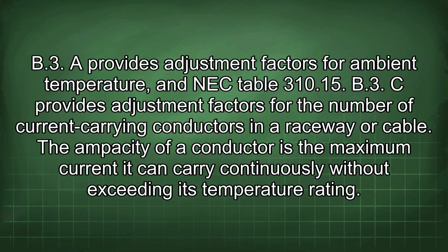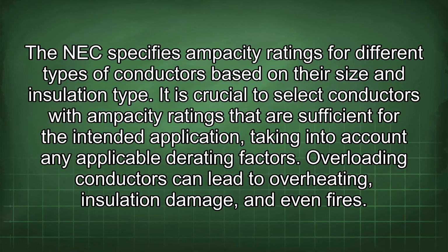The ampacity of a conductor is the maximum current it can carry continuously without exceeding its temperature rating. The NEC specifies ampacity ratings for different types of conductors based on their size and insulation type. It is crucial to select conductors with ampacity ratings that are sufficient for the intended application, taking into account any applicable derating factors. Overloading conductors can lead to overheating, insulation damage, and even fires.